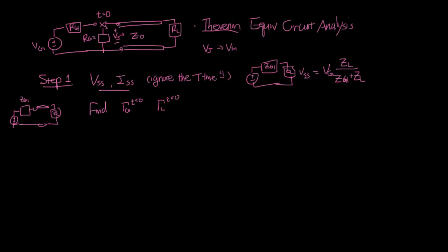So our reflection coefficient, in this case, is just going to be new minus old. So ZG1 minus Z0 over ZG1 plus Z0. And then in this case, it's the same thing that you're used to. So Z load minus Z0 over Z load plus Z0. So the first thing is to find these 4 quantities, which so far you should have down pat. Shouldn't be too bad.